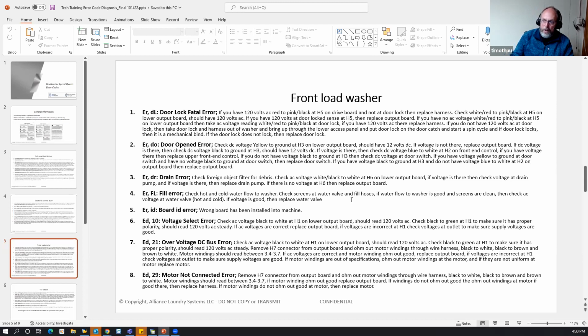And it's bowing in that front panel, which now the top of the door hits and the catch on the door can't get in far enough to do it. So that would be a mechanical bind. You're looking at a front panel on that one then.